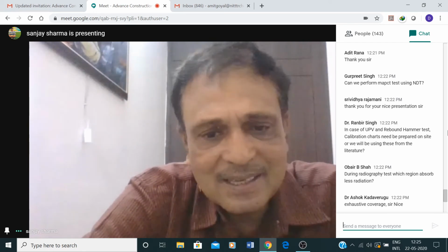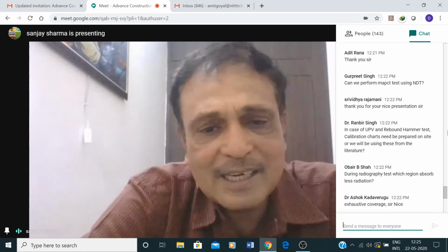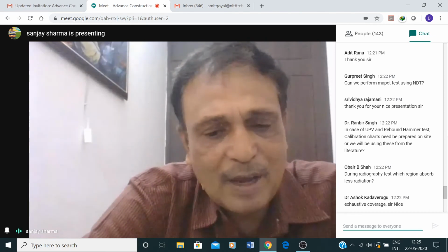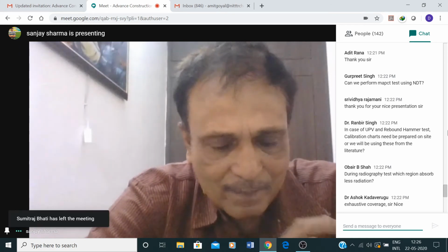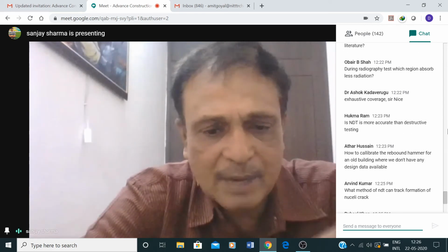So that is what basically interpretation and using these types of tests between the two parties has to be agreeable. Suppose I say that okay, you do a rebound hammer test. If I am getting my bond test carried out at the site with almost these values, with 5 to 10% or 15% variation, I am acceptable to that.